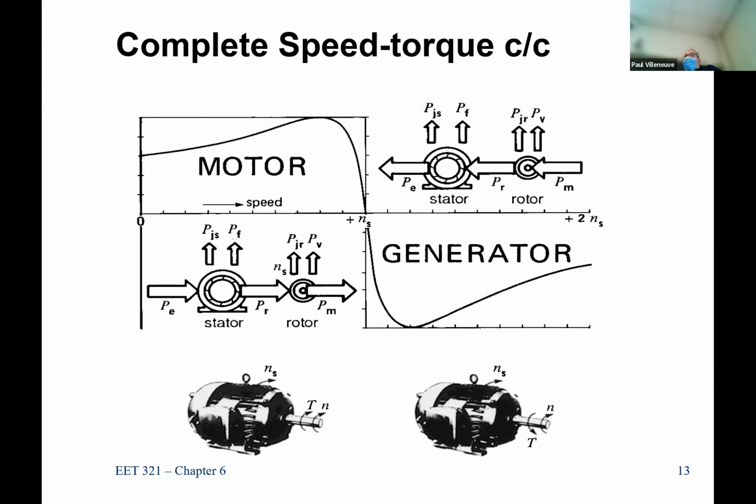Yeah, and the other thing about those horizontal axis wind turbines, all the newer ones are designed to be facing the wind. So you can always tell the prevailing wind direction. The blade is facing the prevailing wind direction. Back in the day, they had these free spinning ones that the wind would push, so it'd always be downstream. The problem with that is the tower itself would block some of the wind, so you're not as efficient. So almost all horizontal axis wind turbines are designed as upwind designs. They're actually facing the wind.